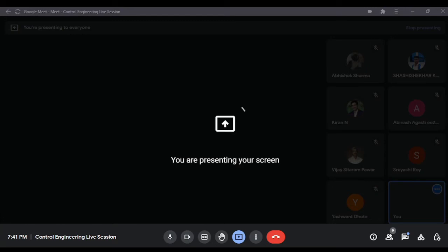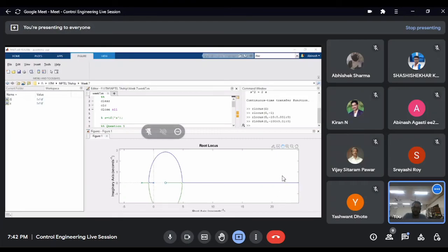Here what you can see is this glitch is due to a slow step value. But if you take a fine enough step value, what you will see is from -2 and 0, the open loop poles, the root locus will come, they'll meet at the real axis, break away, then meet further in the positive real axis, break in, then meet the 0. So that one asymptote will go to plus 0 degree. Is this clear?